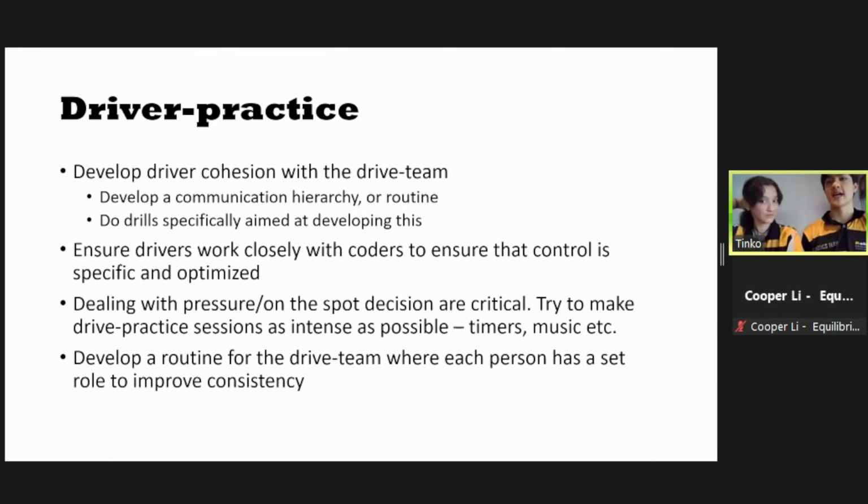With driving, we like to aim for a more smooth approach rather than a jerky approach. We see a lot of new teams and rookie teams bumping and jerking the joysticks. It works, but if you can really utilize the analog control of the joystick to fine-tune the powers to the robot, we think it's better. The main reason is that if you are running a lower ratio or you're lighter weight and you want to go faster to increase the cycle time, then those jerky movements will add to the uncontrollability of your robot.